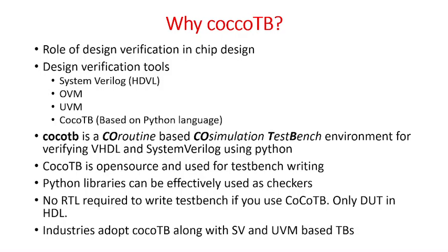Therefore, it has different features like constraints, random constraints. Then we have assertions, immediate assertions and concurrent assertions. Then coverage, right? And because of SystemVerilog's object-oriented programming capability, it can introduce a lot of classes and objects for carrying out test case development in a very structured way. Similarly, it has a lot of inter-process communication elements. So they are very much handy.